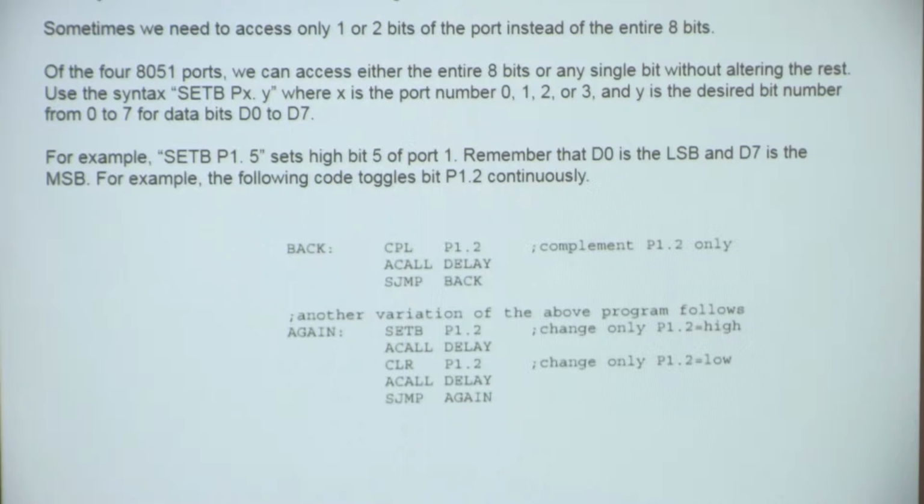So let's look at this little program. I will complement port 1.2. Now, this is just a general little program. Obviously, they can state if it's a program you have to write for the exams. Then they will say, okay, you must first start off with that specific port 1.2 being a 1. Now we just complement it, because they don't say if it was a 1 or a 0.